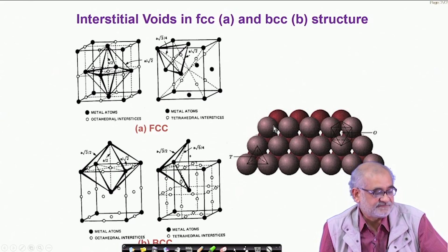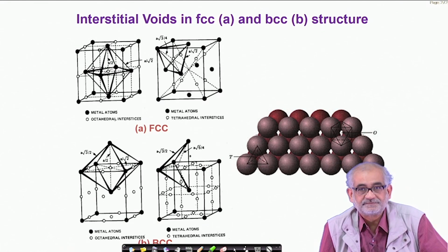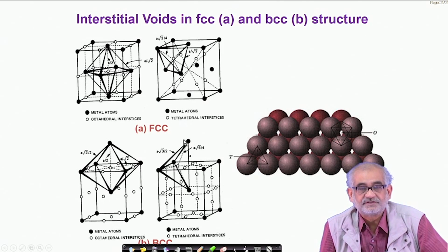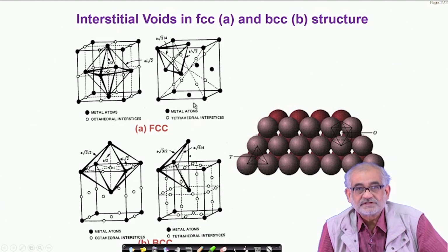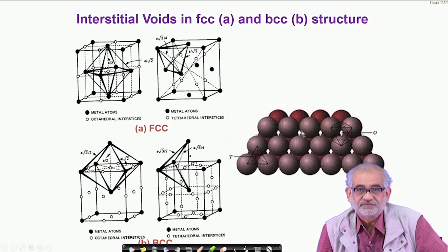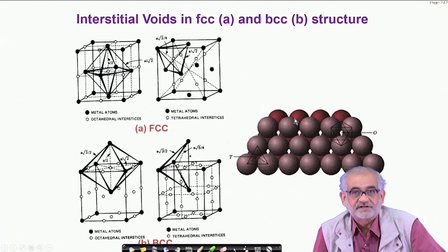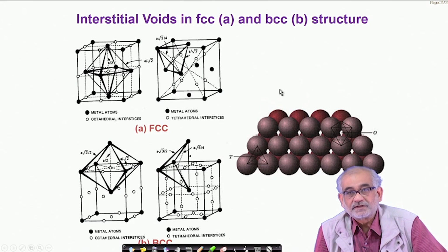The packing density can have very specific values depending on the structure or structural motif that we have. But what is important for us is to realize that the open spaces will also have a very specific geometry, simply because the hard spheres have their own sizes. So if the spheres are of the same size, then the packing density can take very unique values. For example, the maximum could be 74%, or else it could be 68% if it is BCC, and so on and so forth. But what about the open spaces?